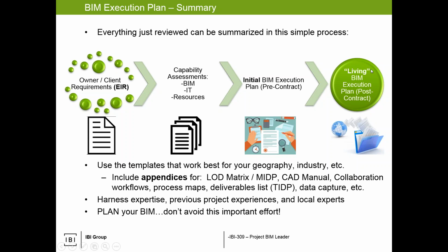And I always say, we always jump right here to the end. Make that BIM execution plan. Have we asked the owner, do they have requirements? Have we assessed our team? And have we made an initial plan to gain buy-in before we get into the detail? Just follow those 4 steps. And if the answer is no requirements, yes, we're 100% capable, great. But at least you've asked the question in order to logically give the answer.